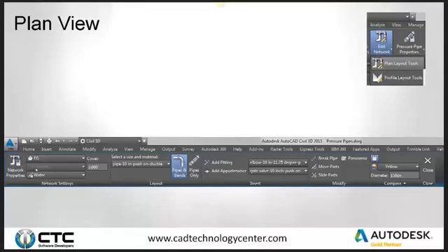I still have almost the same network settings. What surface am I following? What alignment? Parts list? My cover. Right now, out of the box default is 3 feet. I think someone in the Midwest or the middle states, like maybe southern Iowa, came up with a 3-foot bury.